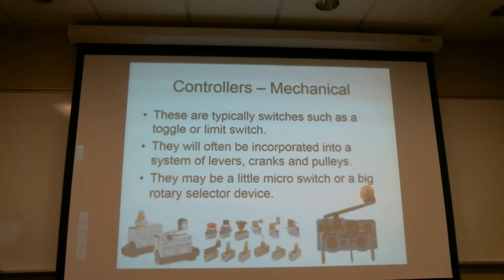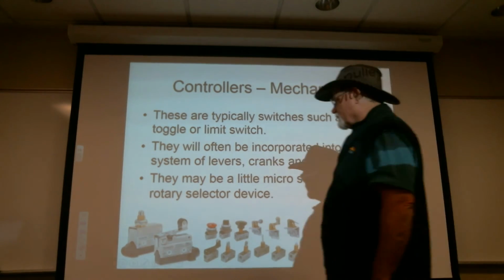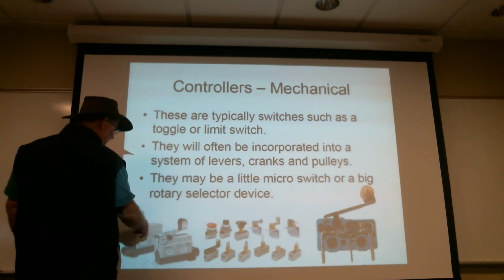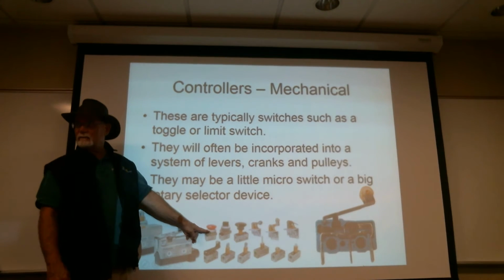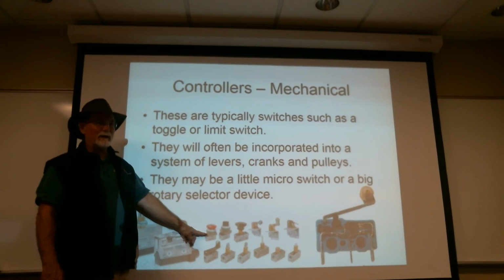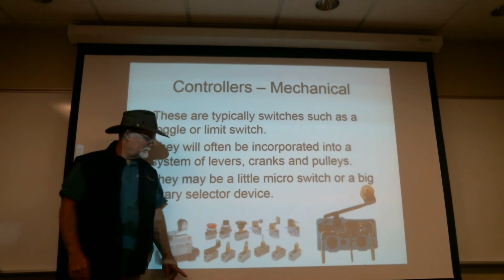Now, the upside of that particular switch, and this is true of many switches, is I could use all 3 of those leads, or I could just not use that second lead, the one in the middle, and it becomes single pole, single throw. Right now it's got a couple of throws. So limit switch there, human interface, that's like the big red panic button. That ain't the easy button, that's the big red panic button.